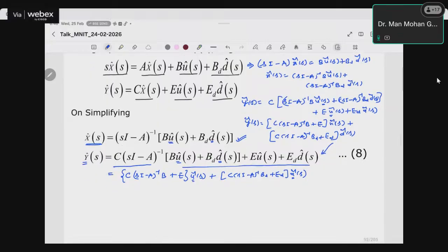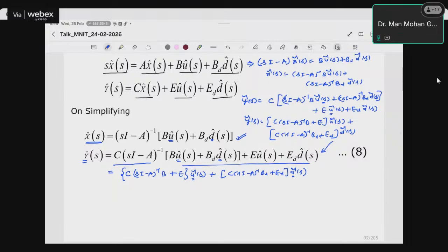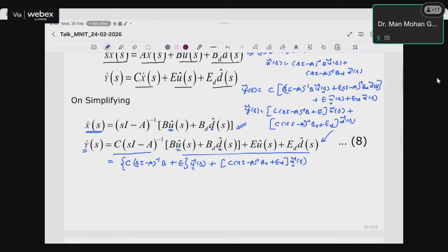So how the dynamics of y will change if there is any variation in u and any variation in d, right? I have already told you what is x and what is y, but what is d? D is the control variable. That is very important, that has to be there. And u is basically the disturbance. So what is the possible disturbance? Possible disturbance is the change in input voltage, and second, the change in load current, I naught or I z, because we have already defined them.